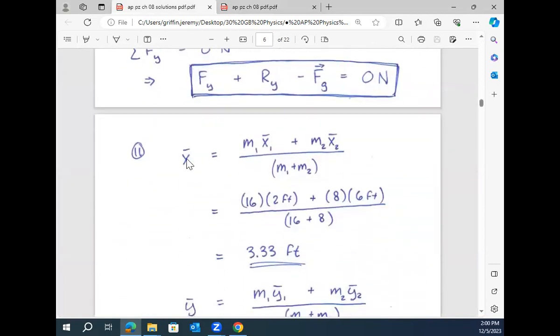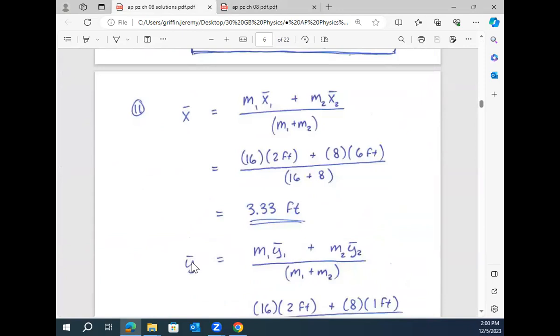So let's scroll down to the number. Here we go. Here's your X bar and your Y bar. Now you have to find the center mass for both the X coordinate and the Y coordinate, and the answer is going to be a coordinate. The way I set it up on the poster, it just did one-dimensional axis, so we have to do X and then Y. Here's the average for the X value. I played off the areas. The 16 I left is unitless, but maybe this is an area, which would correspond to some mass if you multiply by some density. I kind of left that ambiguous.